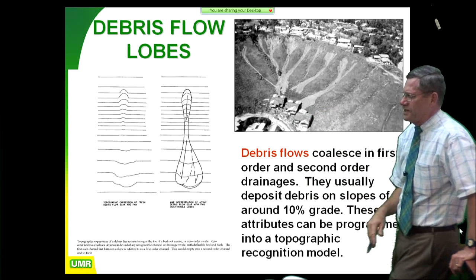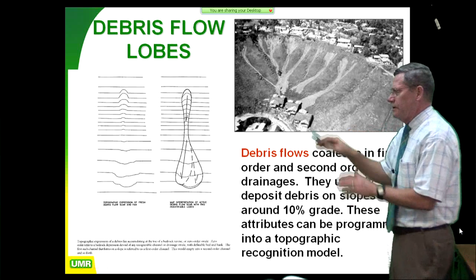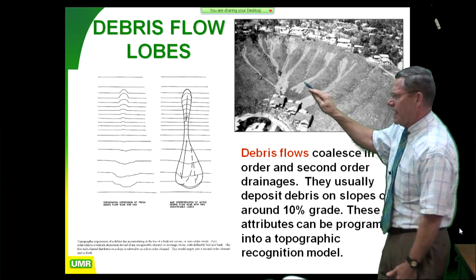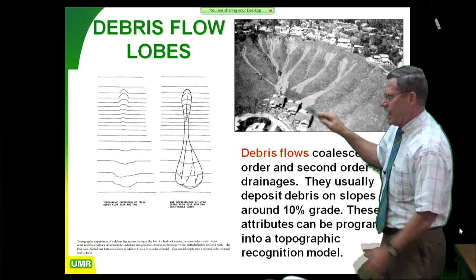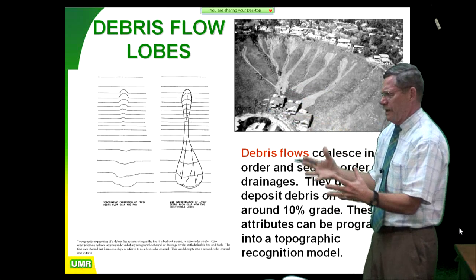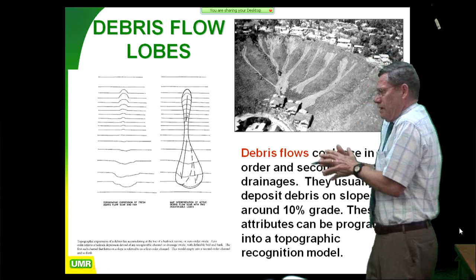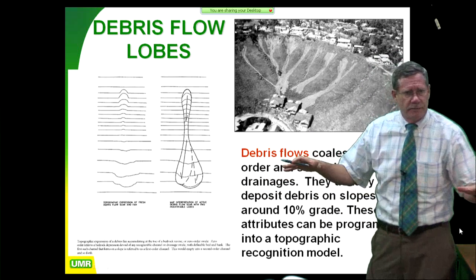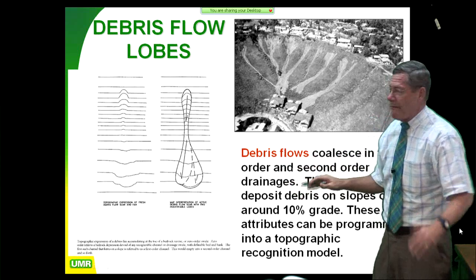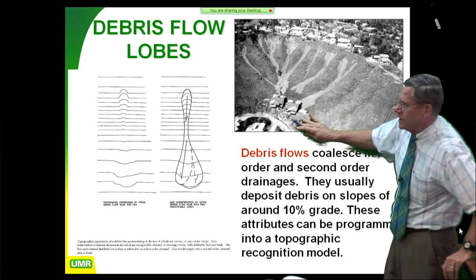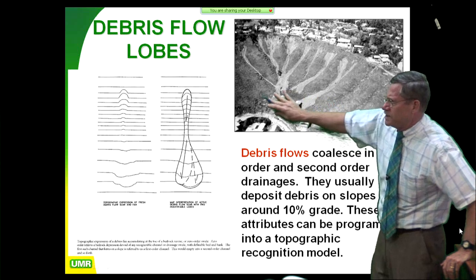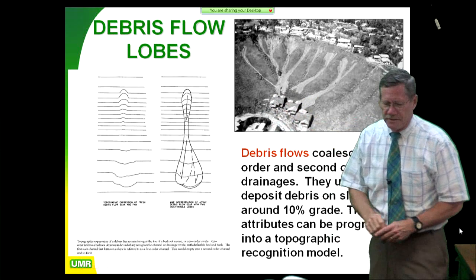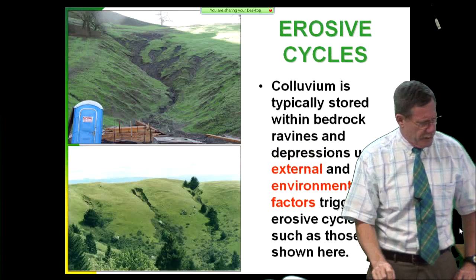Right around 11% grade, that's where these things will come down, no shear strength, they behave as fluids, and then they'll coalesce and bleed off pore pressure and gain shear strength and suddenly stop. Just like epoxy setting up, or like concrete setting up. And it'll be right on the 10% grade area. That's right where everybody likes to build houses. See the houses going in right there? That's right where everybody likes to build houses, especially around Phoenix.